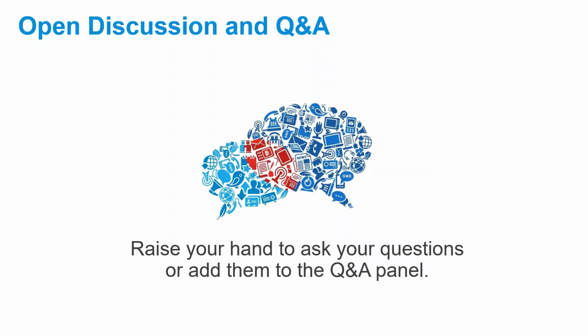Just to go back to Todd's question, the common data environment has been the dream we've all been chasing for years, and we've always been looking for that in a particular file format. Is it DXF? Is it IFC? Is it FBX or whatever? Each one has its own strengths. You might go with FBX if you're going to 3D Studio Max to do some animation. You might use IFC if you're trying to go into Revit to get as much BIM data as possible.